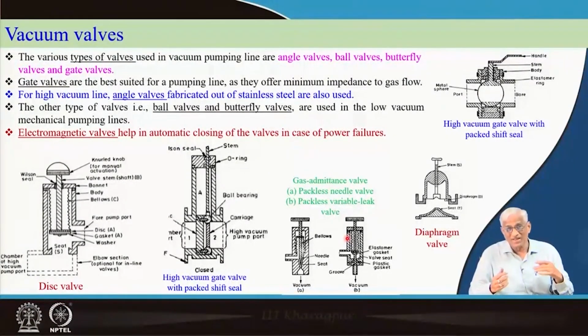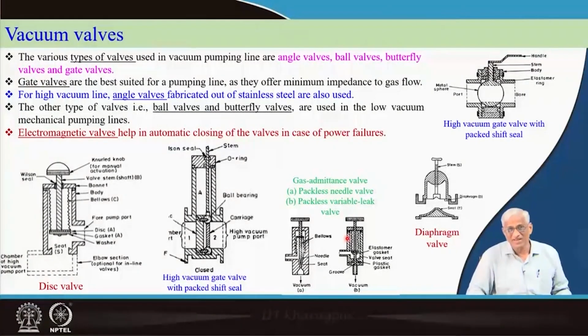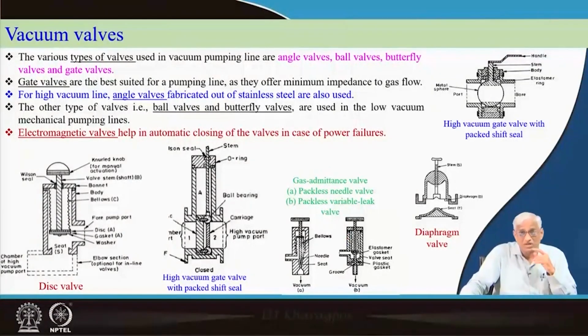When you do that intelligently, you can get fast pump down. If you make a mistake, it can be a leaky system, you can introduce leaks, that is one mistake, or you introduce a very poor conductance, you will not get vacuum. So, components should be chosen like that, but valves are required to isolate at various timings. So, valves are very important components in high vacuum technology.